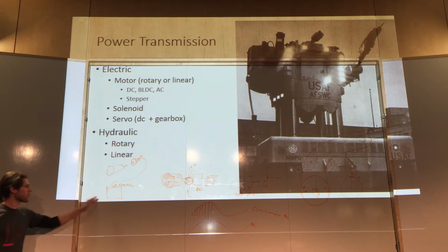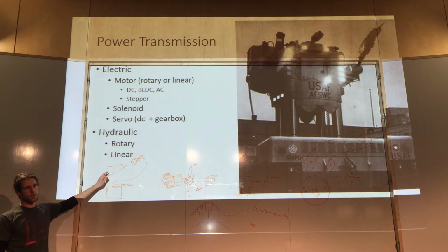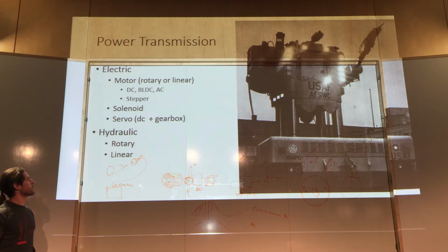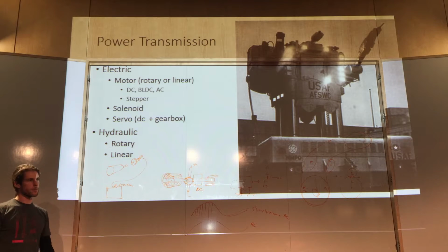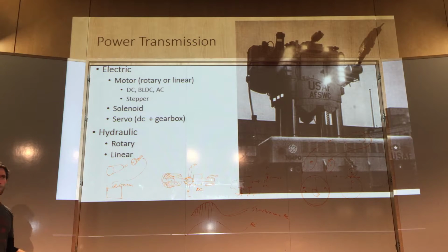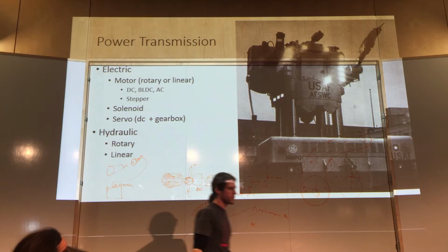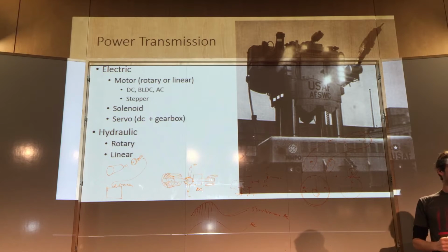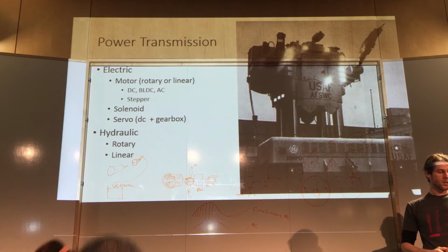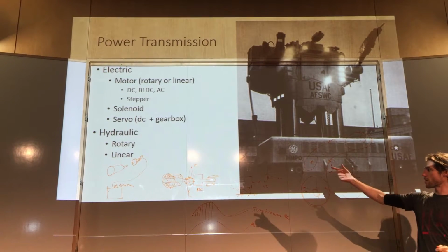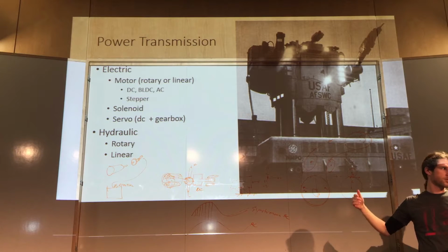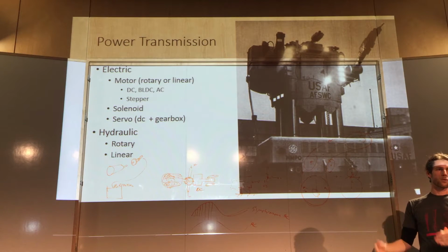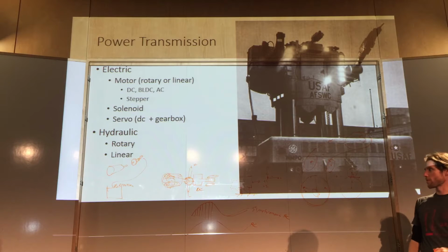So anytime you need high precision or real power generation, go with the DC or brushless DC motor. A super high-end manufacturer that all robots have is Maxon motors, and they're like $600 a motor, but you get what you pay for. And now there's a big interest in hobby outrunner motors, which you've probably seen on all the quad rotors that people have nowadays. Those are brushless DC motors, but they generally have a really low inductance, so it's a different type of motor than is normally driven. Off-the-shelf options for driving them in servo position control barely exist.